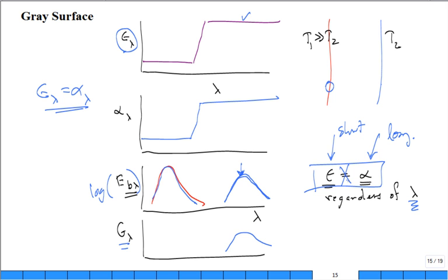It's going to be sending them out at 300, 500 Kelvin. I don't know what the temperature of your collector is, but it's going to be sending them out, right? You would like it not to send them out very well in those longer wavelengths. So absorb very well in the 0.2 to 2 micron, but don't send them out in the 4 to 40 micron. So you would just want the opposite.